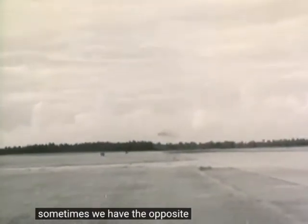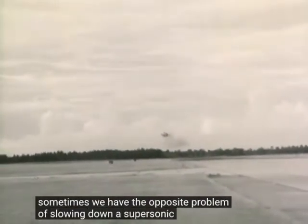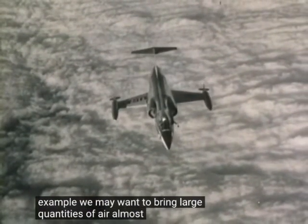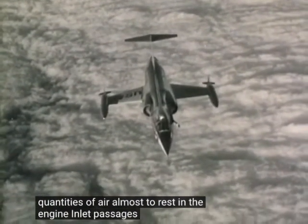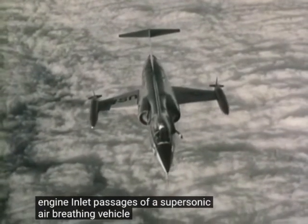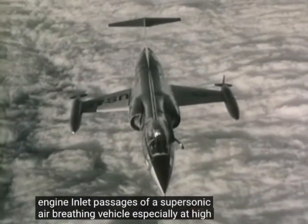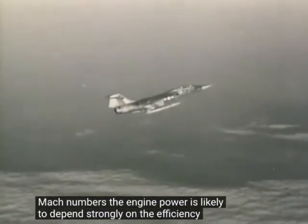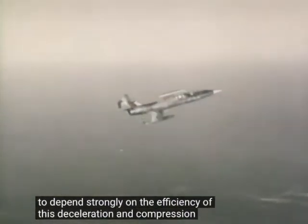Sometimes we have the opposite problem of slowing down a supersonic flow. For example, we may want to bring large quantities of air almost to rest in the engine inlet passages of a supersonic air-breathing vehicle. Especially at high Mach numbers, the engine power is likely to depend strongly on the efficiency of this deceleration and compression process.